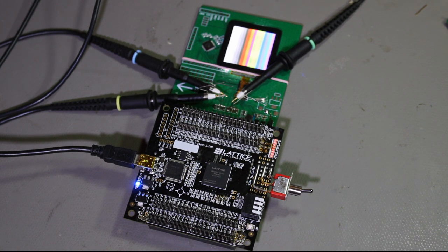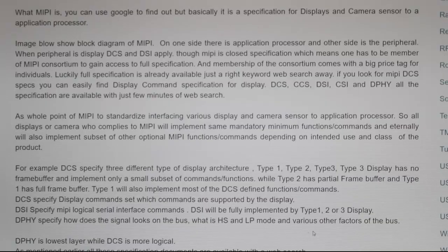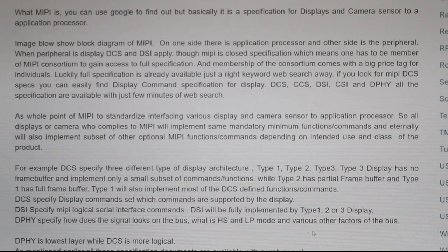In this video, I'll show you how I connected this LCD to a PC over USB using a PIC32 high-speed USB microcontroller. This microcontroller will take data from the USB application and transfer it into the FPGA over 50 MHz SPI, and the FPGA will ultimately take that data and push it onto the display using MIPI. The complete details about this project are available on my website www.circuitvalley.com. Complete source code for the FPGA, the USB microcontroller and the PC application is also available in my GitHub account.